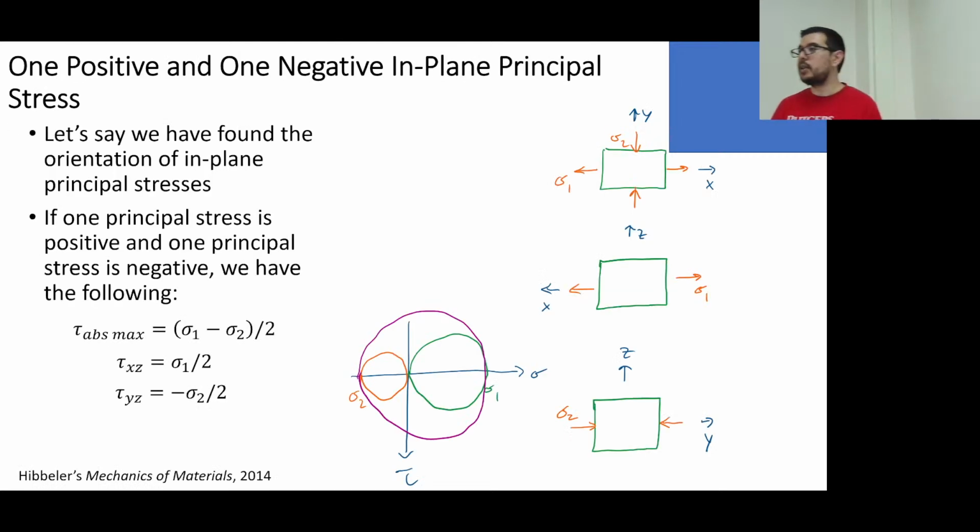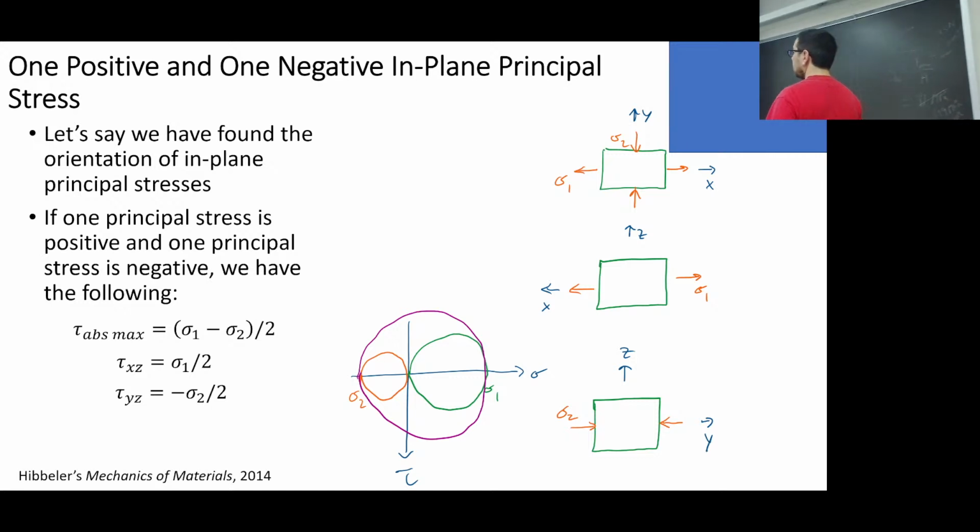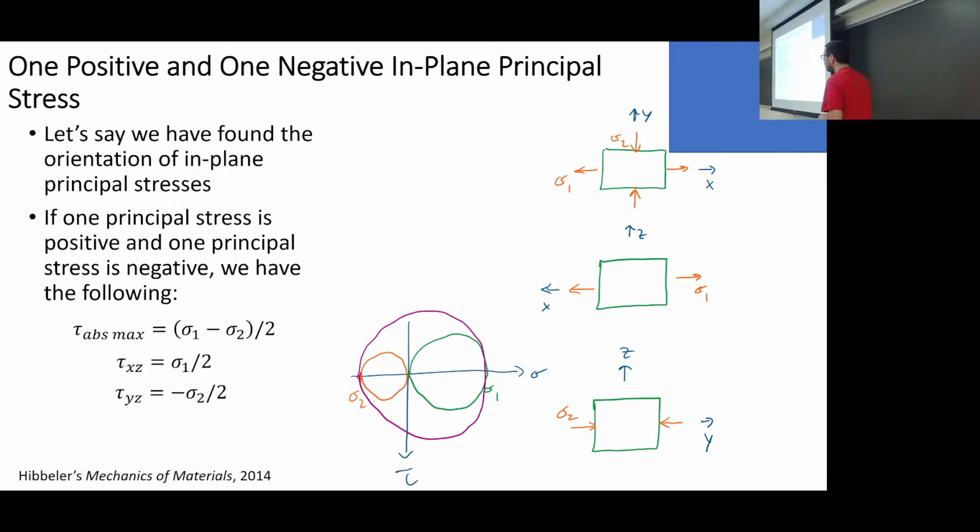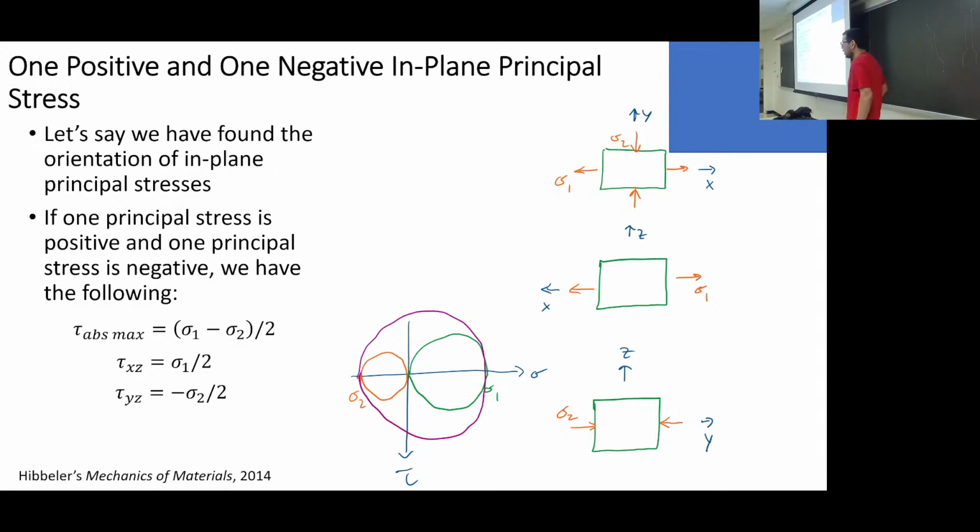Any questions, any thoughts? Yes, Joshua. I noticed that the stress is positive even though it's in the negative x direction initially. So it's just based on the direction relative to the face. Right. So yeah, again, I probably took a little bit of liberty here. I'm trying to show that it's a compressive stress, and I'm kind of trying to have it both ways. More technically correct would be what you've just pointed out: I draw sigma 2 going out, and then I just say sigma 2 is less than 0.